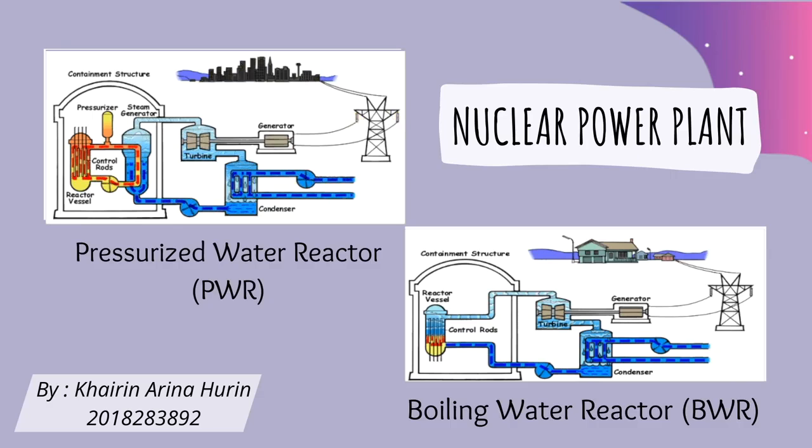Both of these reactors use enriched uranium as a fuel and water as a coolant and moderator to slow down the neutrons. The pressurized water reactor, or PWR, has water over 300 degrees Celsius under high pressure in its cooling heat transfer circuit and generates steam in a secondary circuit. The boiling water reactor, BWR, makes steam directly by boiling water coolant. The steam is separated from remaining water in a steam separator positioned above the core and passed to the turbine. Then, the steam is condensed and recycled.